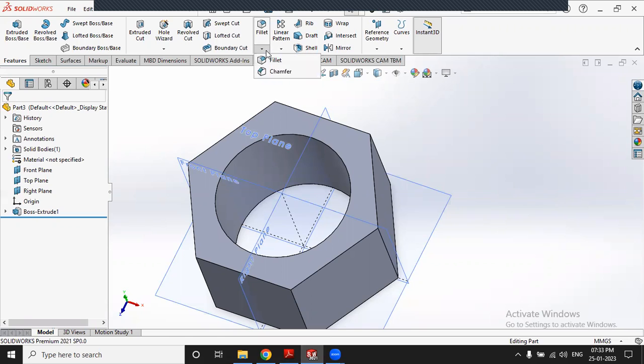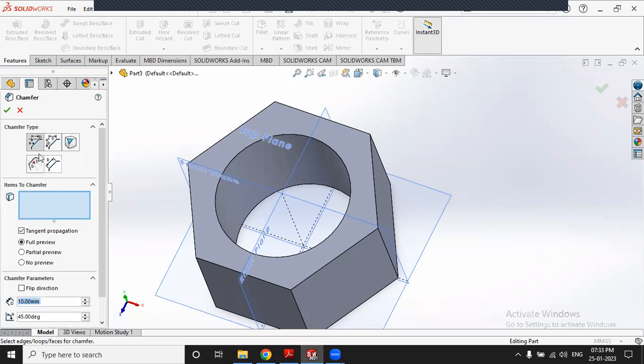Then I will go to chamfer and select distance. In distance, I want symmetry. Because it's 0.03 multiplied by 0.03, if I assign one dimension on any one side, the software will assign automatically on the opposite side. Then it asks for items to chamfer, or edges to chamfer.